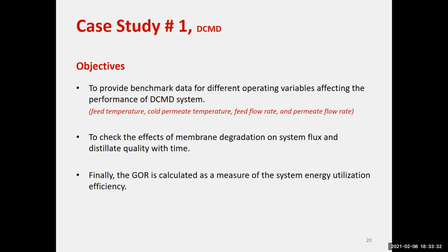The good thing about the membrane distillation system is that you can buy a flat sheet of membrane, which is 15 by 15, but it should be a hydrophobic membrane, not hydrophilic, not the membrane used for the RO system. So we used to buy sheets of the membranes, and sheets of plexiglass or acrylic, and build our own units ourselves here. We used to design and fabricate them in our workshop in building one, and then test them, operate them, and modify, and operate and modify. And that's the way it goes.